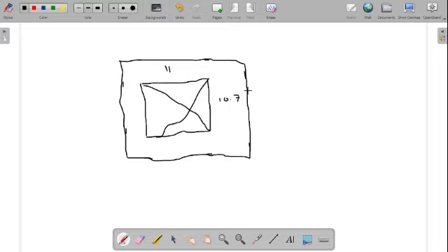Now these are setbacks created to position our pegs such that when we are excavating the trench for these building lines, this profile will not collapse due to soil caving because it is too close to the excavation trench. Now, with this being said, the distance we have between this point and this point is 1.5. Also, the distance we have between this point and this point also is 1.5.